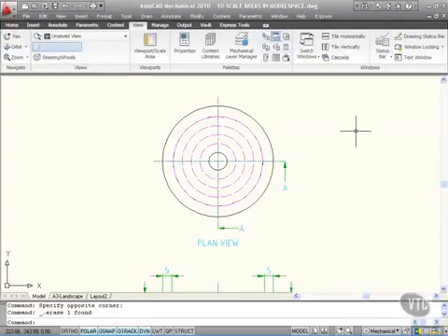Now, when you're working in Modelspace in AutoCAD Mechanical, you can actually set up scale areas in your Modelspace. Previously we've set up named views. These are subtly different. Basically you're creating a full size view in the model, so in Modelspace it will be full size, but you're telling AutoCAD Mechanical what scale you want that view to be in your layout tab when you create a viewport from that scale area.